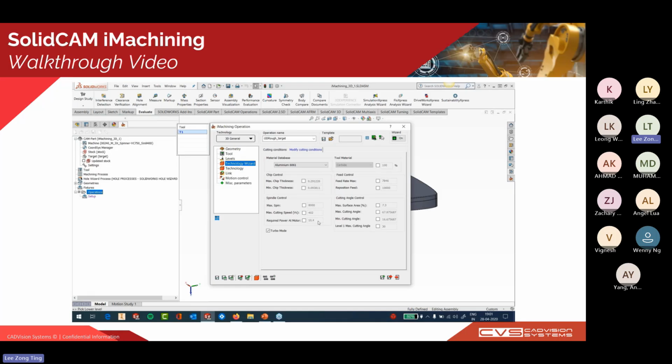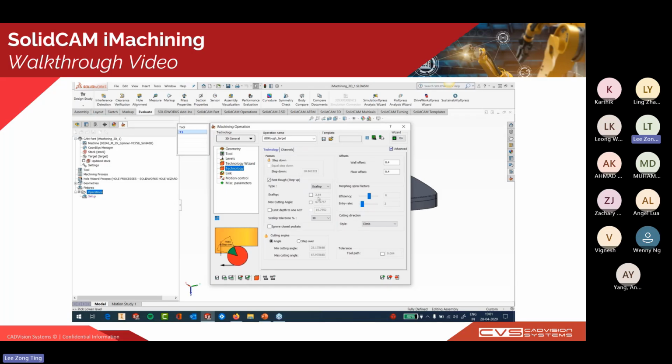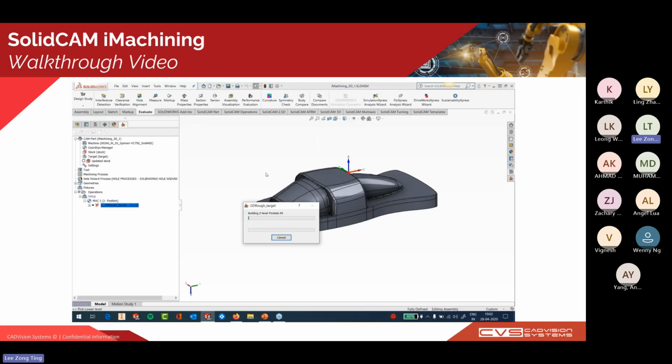And we can check that our motor is operating at 10.4 kilowatt. We don't want that, so we can go ahead and modify it to, for example, 7 like just now. All right, after we change it, you can see the spin rate and feed rate have changed. Also, one interesting feature in iMachining 3D is the scalloping strategy to rough those slanted surfaces. Later in the simulation, you can see what it means.